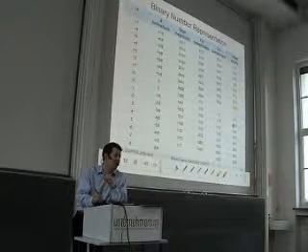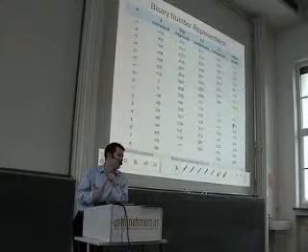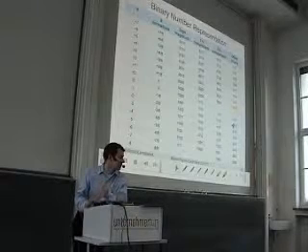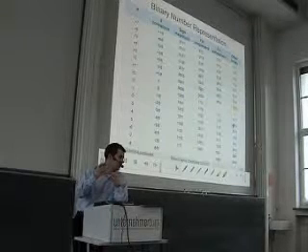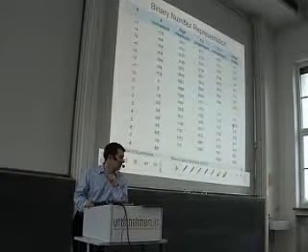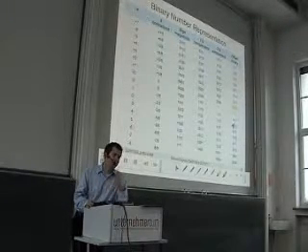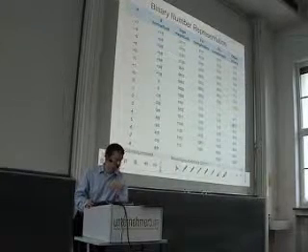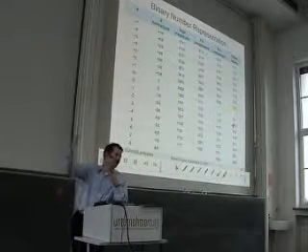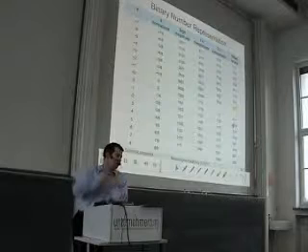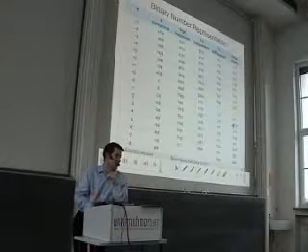This occurs very often in algorithms that do actually not see the sign. We will see that this occurs in the successive approximation converters, where the definition of positive or negative signals is somehow arbitrarily chosen, or not arbitrarily, but is chosen somewhere. And then it occurs that if the value is very small, we get all 0s. If the value is very large, we get all 1s. In between, we get all numbers. And to end up with an appropriate interpretation, we have to subtract this.